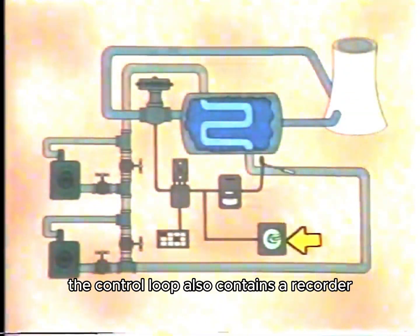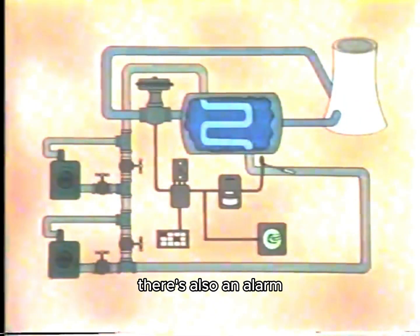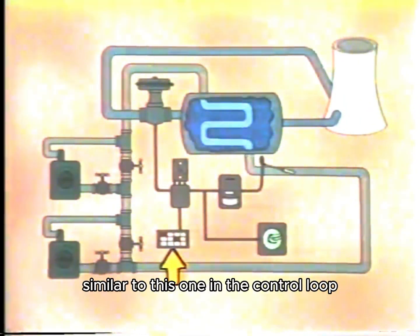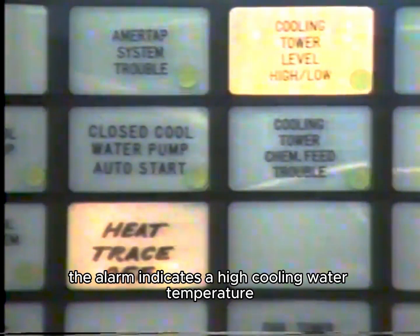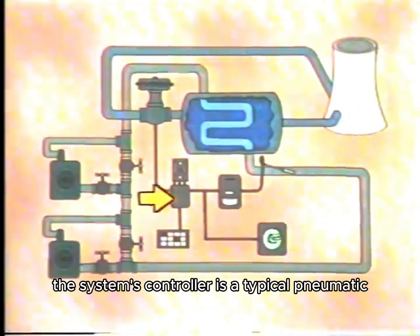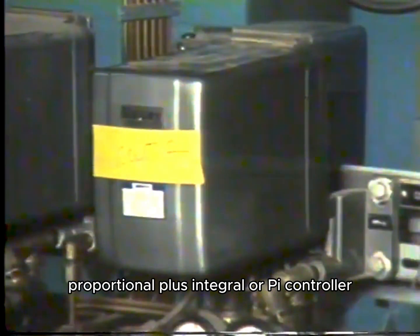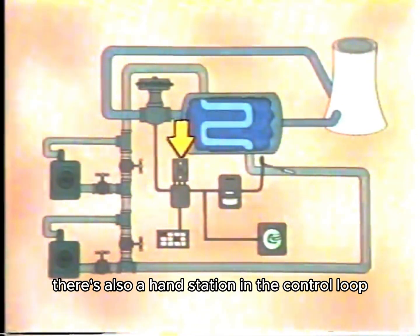The control loop also contains a recorder. The recorder documents the value of the cooling water temperature. There's also an alarm similar to this one in the control loop. The alarm indicates a high cooling water temperature. The system's controller is a typical pneumatic proportional plus integral, or PI controller. There's also a hand station in the control loop.